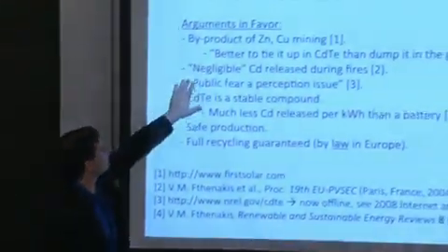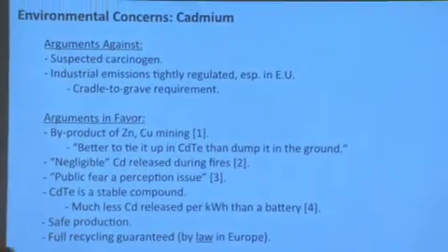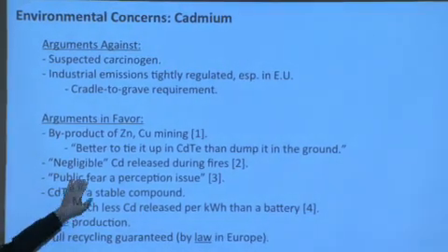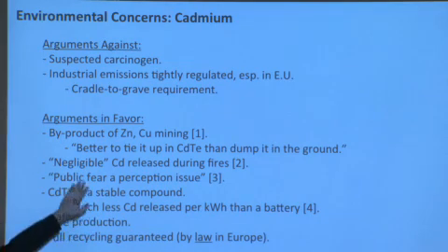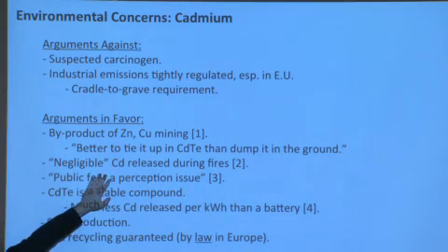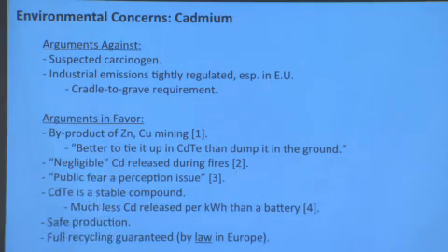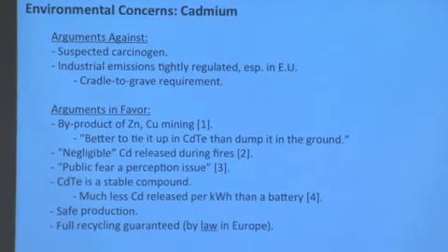The argument in favor of having cadmium inside of solar panels is the following: it's better to tie up cadmium inside of a relatively inert compound, CadTel, than to have it go off and cause problems on its own. If you heat it up, the CadTel would evaporate congruently. Typically, so-called negligible amounts of cadmium are released during fires, and I put it in quotes because these are studies, very good studies, and I trust the work coming out of Fthenakis' group very much.